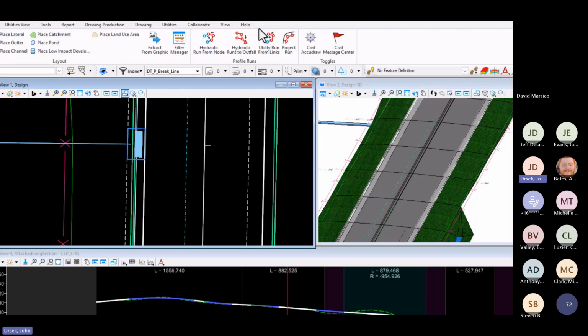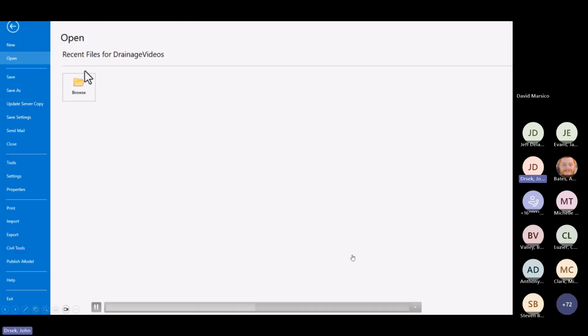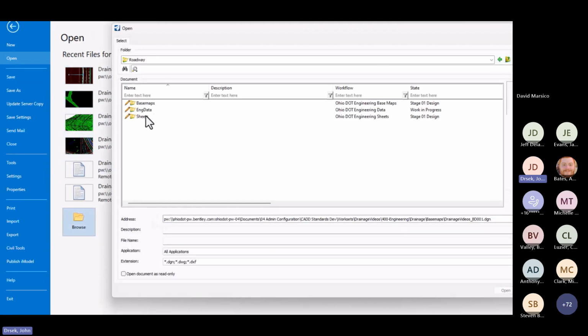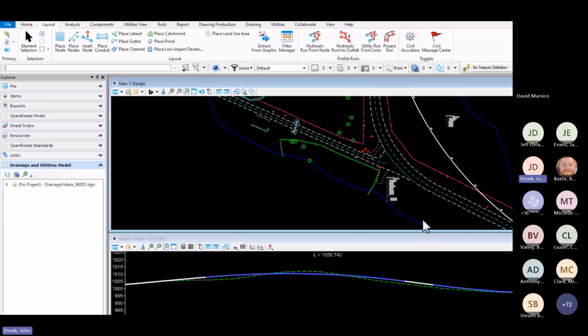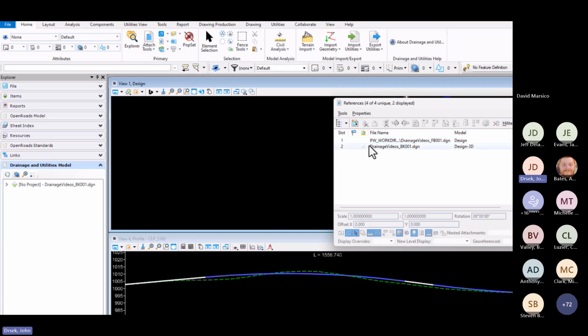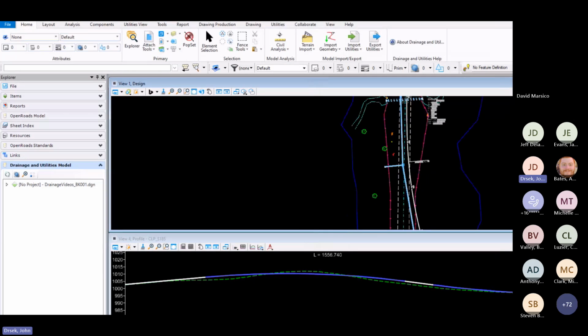That way, if you wanted to see your drainage work in your profile view, you would just hit attach all profile views, so you didn't automatically get drainage every single time you looked at that profile. All right, so we don't get that control anymore. Now it's going to show up on our centerline profile every single time, and we have to turn it off every single time on all of our sheets. But that's what we have to deal with. So in order to do the projection, we have to go to our alignment file. Now there's no way around it.